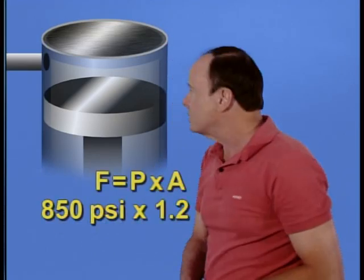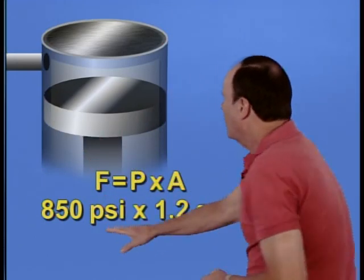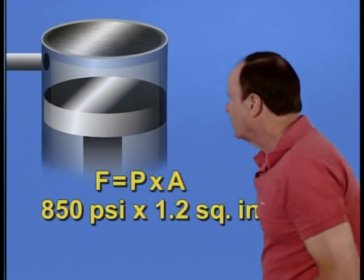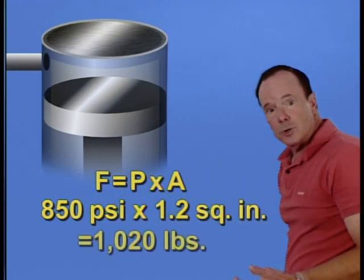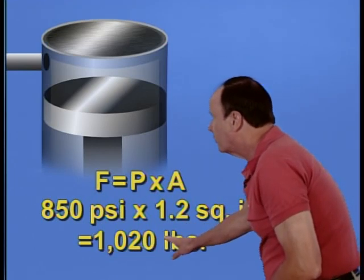Now, let's take a look at a couple of questions they're going to ask you, and let's take a look at the first one here. They're going to say you have a piston with an area of 1.2 square inches, and it has 850 pounds of pressure. What is the force put out by this piston? And the answer is force equals pressure times area, so it's 850 psi times the 1.2. You just use your calculator to multiply that out, and you get 1,020 pounds.